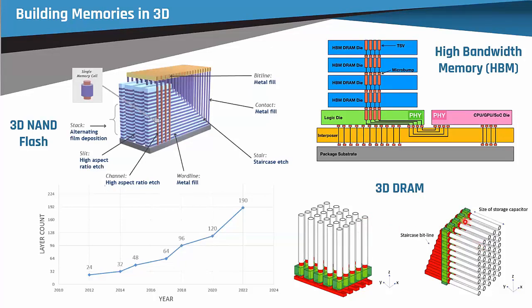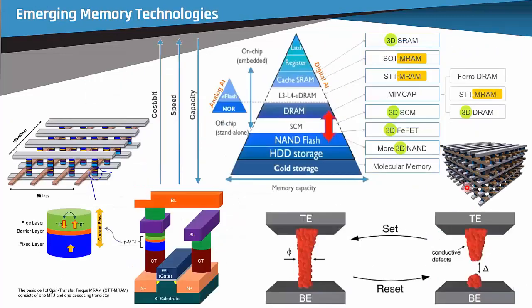Well, why not just turn it on its side? And then you can make as many stacks as you want on top of each other, and each one of these is a cell. And the area doesn't matter how many of these are stacked on top of each other. It's going to still take up the same area for a single stack of DRAM. So that's something that they've been working on for quite some while, and it might be another way to get much higher density in DRAM.